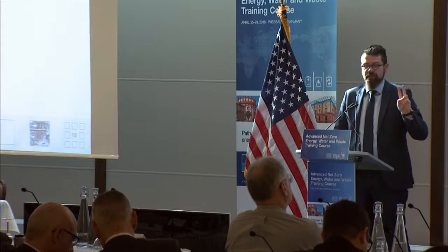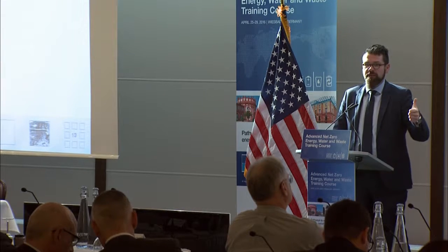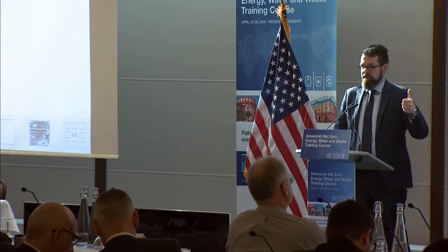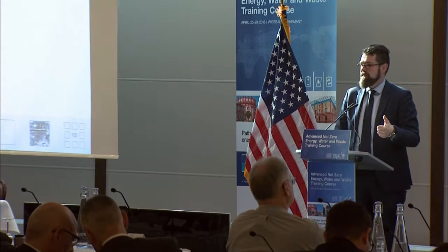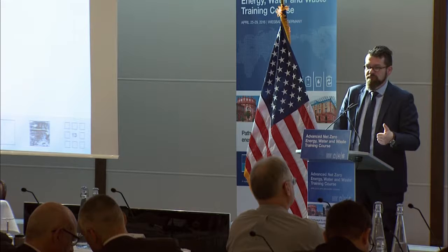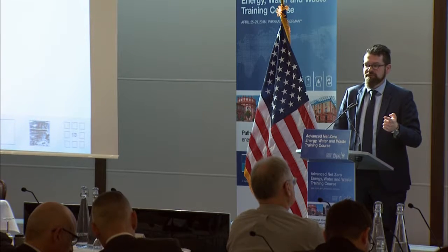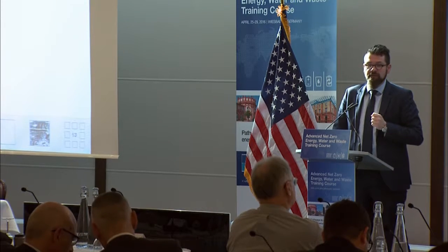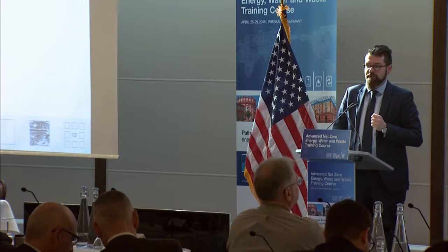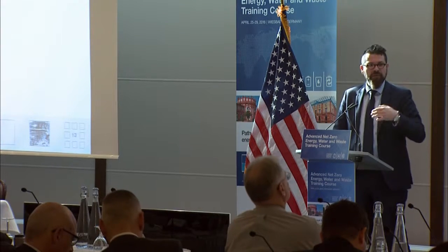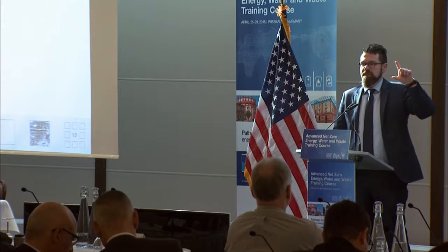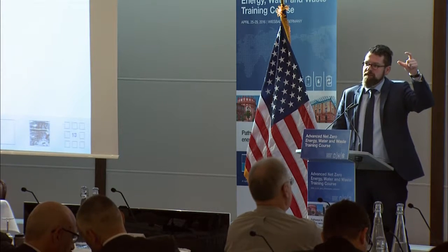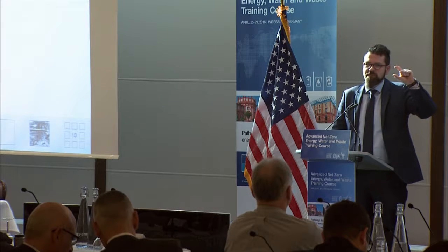So we have 2 economic impacts. The first thing is in a district heating or cooling system, we have this economy of scale compared to a single building heating system, and we can benefit from the coincidence factor. And also the operation of the equipment is more efficient if we have different load profiles and we bring them together, and the delta between peak and minimum point is smaller.